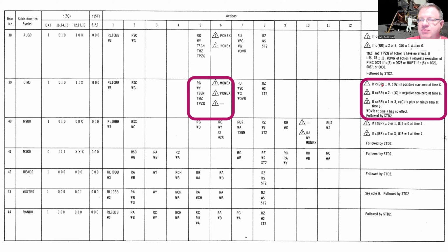So if that branch register, those 2 flip-flops, contain a 0, it's because we've executed one of these tests. We will then execute this. If the branch register contains a 2, we will do this. If branch contains a 1 or a 3, we won't do anything.